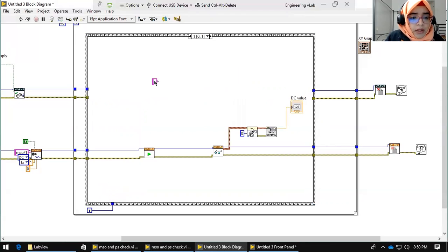Here I'm going to write down: we are going to measure current I across the resistor equals VS, which stands for V supply, minus V across the diode, VD, over R. You're going to divide the entire term by the resistance.